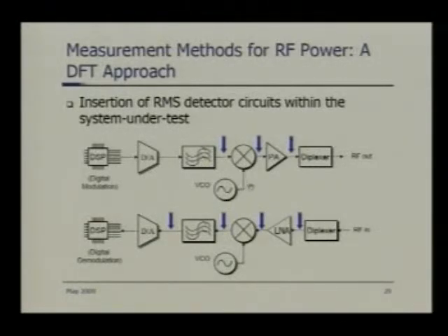So if the VCO is, say, 1.9 gigahertz, it will take the low frequency baseband waveform or low IF waveform and frequency up convert it to the 1.9 gigahertz around it, right? So that is the basic principle of the mixer. And then you boost the power level of the RF signal using a power amplifier and send it through the diplexer.